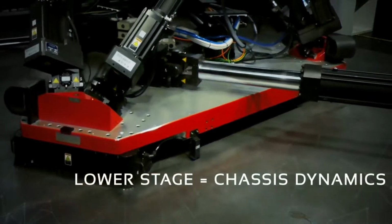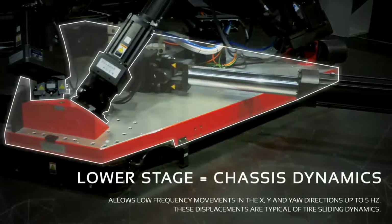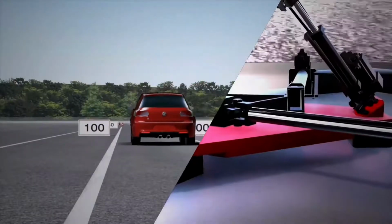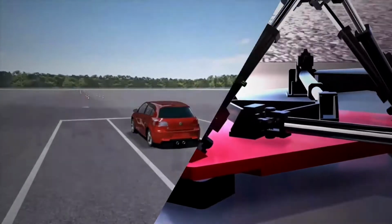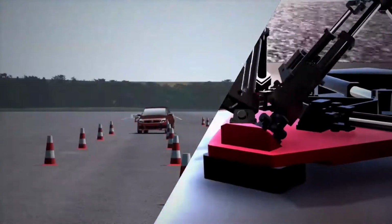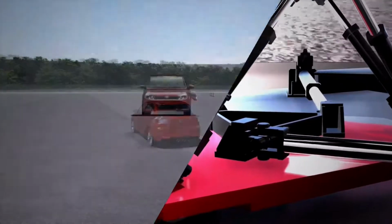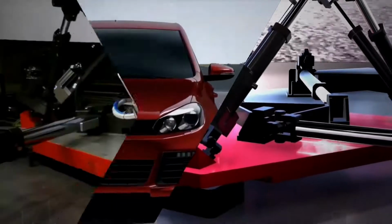Because the lower stage is designed to give you all the feedback you need for chassis dynamics. It's X, Y, and yaw response up to 5 Hz, and it's very adapted for all low dynamics maneuvers, sliding dynamics, and so on. As you can see, for a lane change, for example, this stage will be dedicated to give you the low dynamic response of the maneuver. So you have a dedicated stage for this.